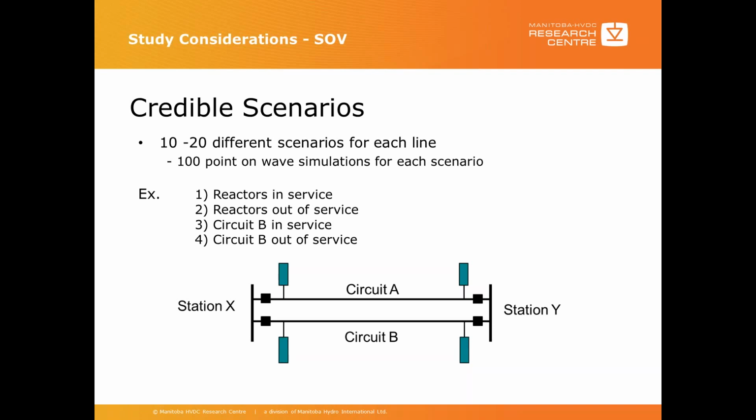Also, you can consider the scenarios when the other lines coming into the stations are in service or out of service to capture the worst case possible.